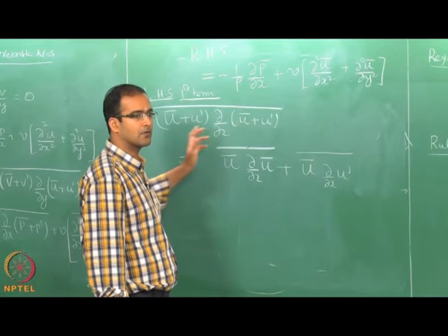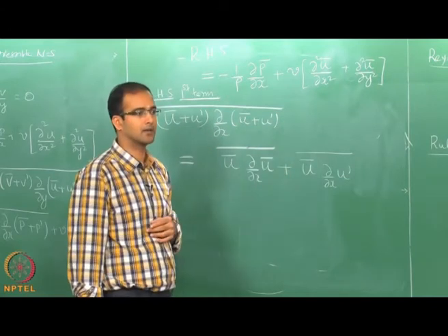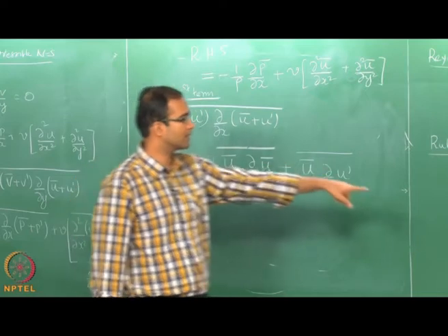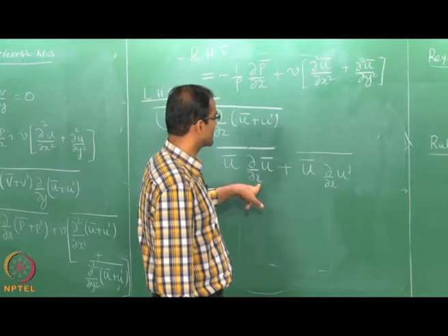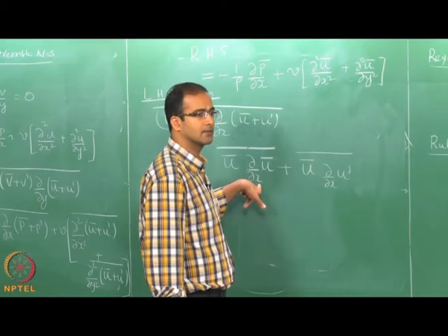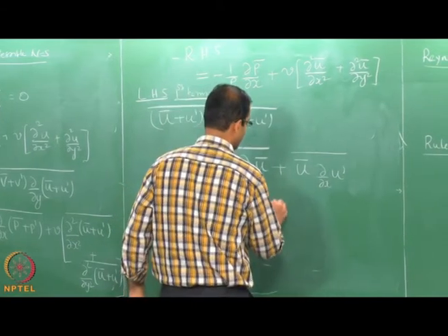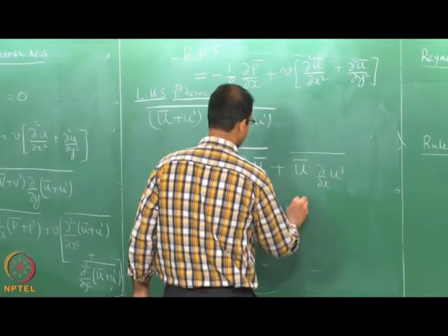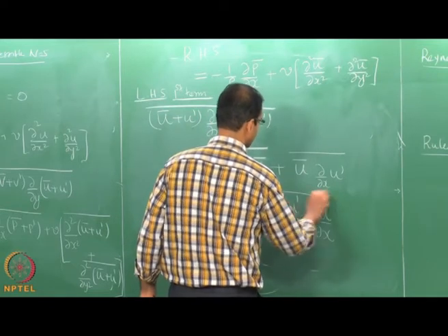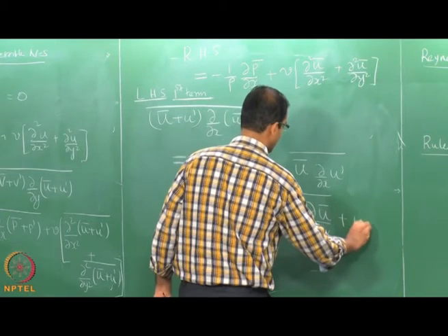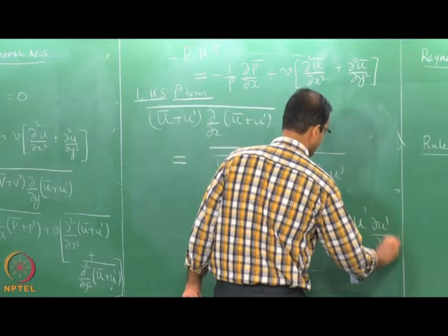So, we have to first multiply the terms and then apply the individual averaging operator. Now we will go back to the averaging rule which says that we can apply the averaging operation to these independent things. Now we have two more terms left. One is u prime into du bar by dx, whole bar, plus u prime du prime by dx, the whole bar.